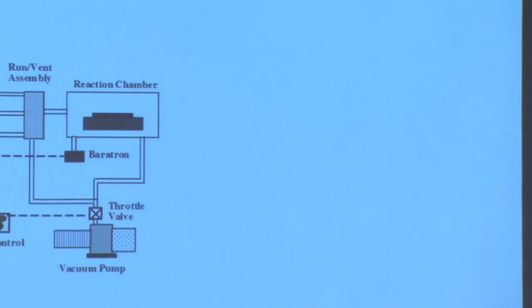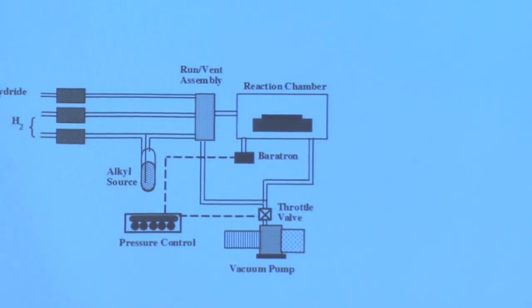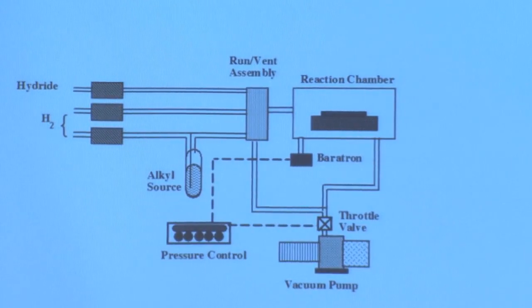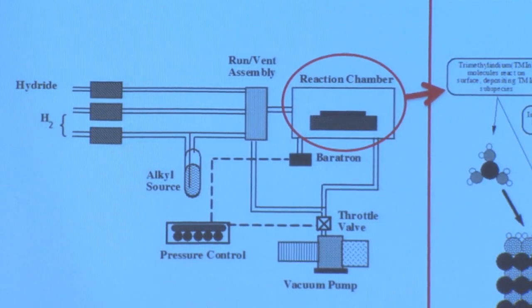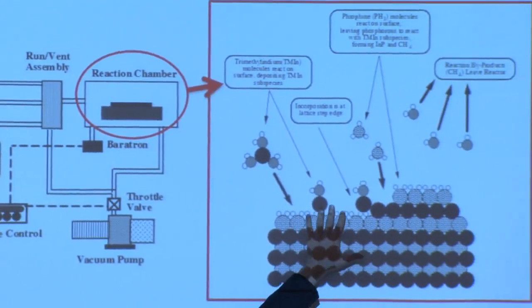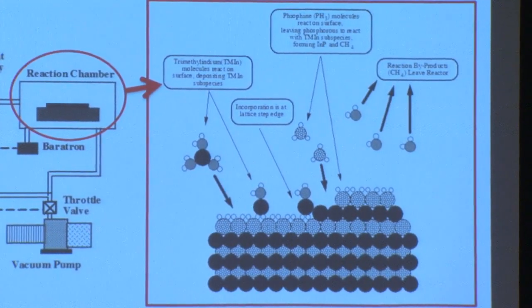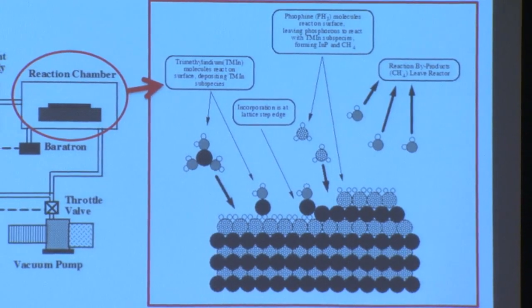And what we do is we flow these molecules into our reaction chamber and control the temperature gradients inside in such a way to have those molecules deposit on the surface, leaving the indium behind, or the metal behind, and the reaction products float away out the back. That is represented chemically here on the surface. This is zooming in right at the surface of our sample, so right where the gas interacts with the thin film material that you're depositing. This is representing the incoming metal organic molecule, right, reaching the surface.